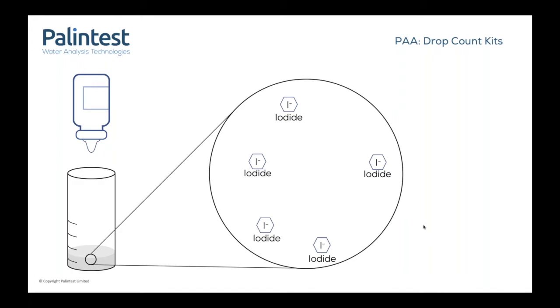But there are some fundamental chemical limitations to this. The first is hydrogen peroxide. So anybody using PAA in a food and beverage setting will know all blends of PAA are made of equilibrium mixtures of the peracetic acid, hydrogen peroxide, and acetic acid. And for many mixtures, the hydrogen peroxide is actually present at a higher concentration than the PAA. So this interference can be very significant.